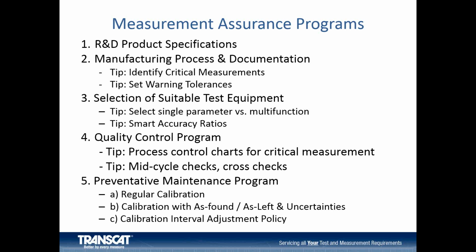For your quality control program, think proactively. Think about process control charts for these critical measurements. If temperature is a critical measurement in your process, maybe you ought to do something else to monitor that to prevent you from having to do this. Think about mid-cycle checks, cross-checks. And have a very good preventative maintenance program. Really, calibration is a preventative maintenance function. It's like insurance. It's nice to have, but boy, it's really nice to have when you need it.